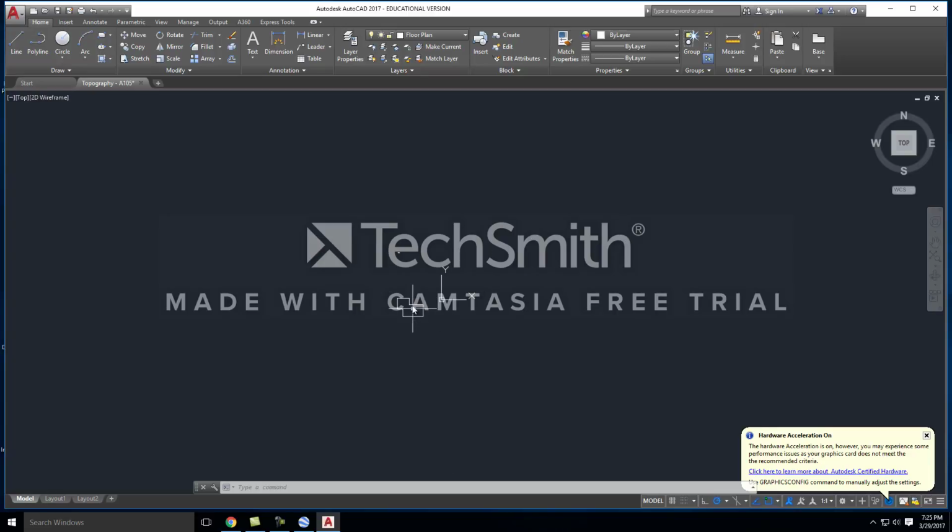Can we scale things down once they've already been made? You can. There is a scale tool. I'll show you how to use it. It's very easy. You select the item that you want to scale, click on scale, specify a point, and then you can just type in a scale factor, like 0.5. That will make it half the size.